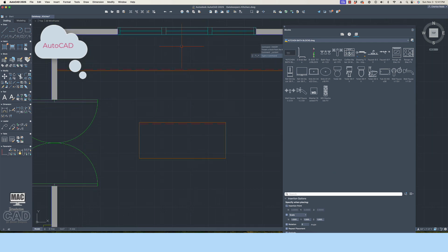We will place the apron front sink first. Establish a vertical construction line for the placement of the sink, centered on the middle window. Locate and double-click on the Plan View Sink icon in the block library. If the OSNAPs place the sink in an unexpected location, use the Move command to center it to the front of the countertop line as you see me do here.